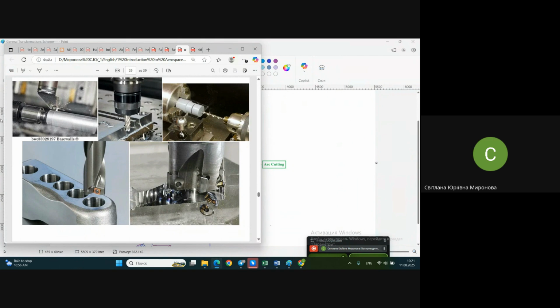Look, the process which is called turning. The blade moves linearly, and the workpiece is rotated, turning or lathing. While turning, you are cutting a layer of material by spiral motion altogether. It looks like spiral motion of the tool along the workpiece, but really the spiral motion is a superposition, a summing of linear motion of the tool and rotational motion of the workpiece, turning, or another name in English, lathing.